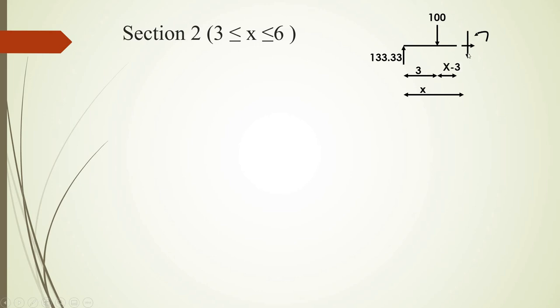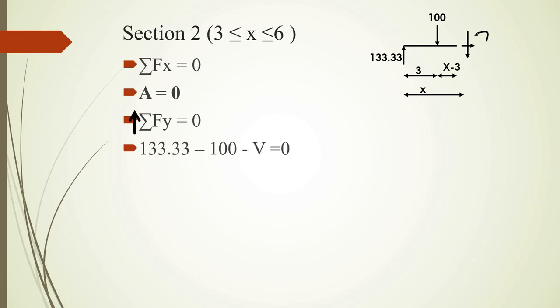Again, you can see the internal forces being exposed, the axial one, the shear, and the moment. Again, we'll apply summation Fx equals 0. I'll go a bit quicker now. A is 0. I'll apply summation Fy. I'll take upwards as positive.